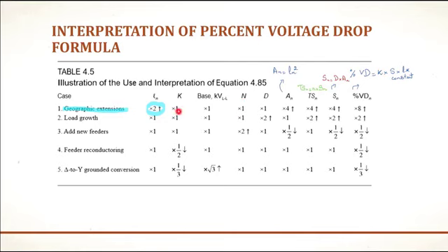These three are not going to be changed. We are not changing the load. That's why this D is also not going to be changed. Now what is the impact on the area? As I have told you, area is equal to the square of the length. So if the length of the feeder is being doubled, it means area will become 4 times.